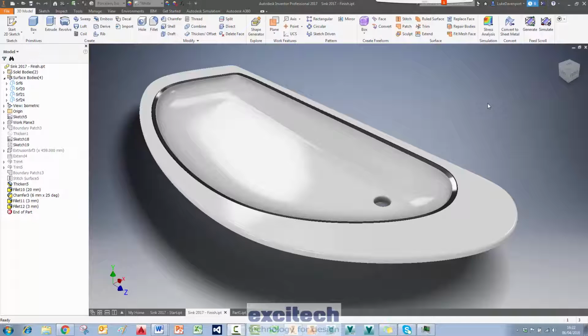and, more importantly, flexibility. Because the problem with the loft tool in Inventor, or just the way that lofting works in general, is its profiles and rails. And your rails need to intersect your profiles, and if you get that kind of thing wrong, it's not flexible and it's going to kick up a big fuss.